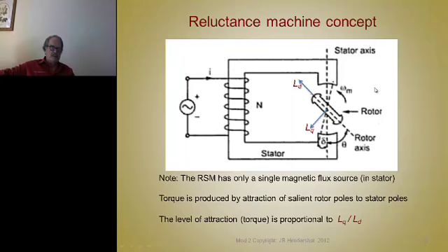For example, when you're generating, you allow a little current to flow, a little low voltage across the coil when you're in this position, and then the prime mover rotates it till it's in that position. Then you open this circuit, and you will get an output that's equal to the input times the ratio of these two inductances. That's what you'll see through the flyback diodes in the power converter circuit that'll go back on the DC rails. You'll get a voltage that's multiplied by this inductance ratio.